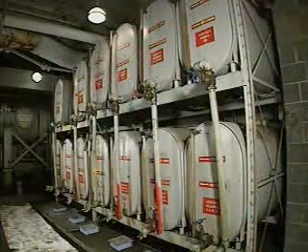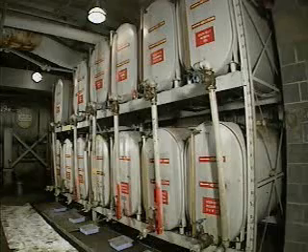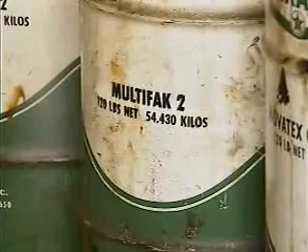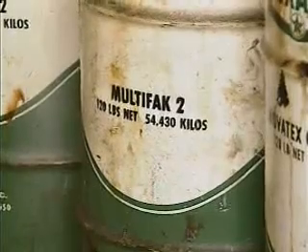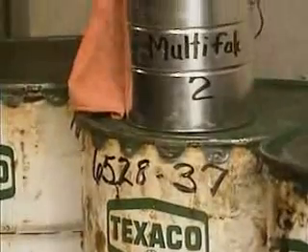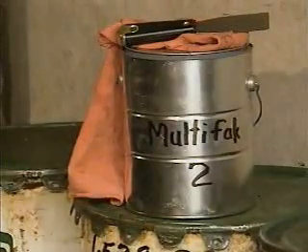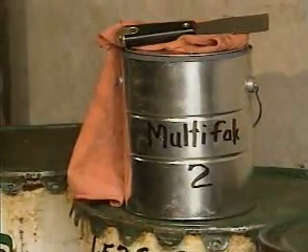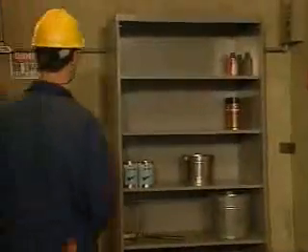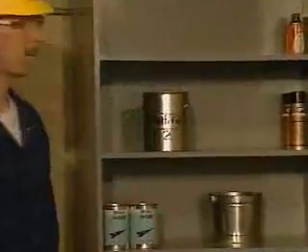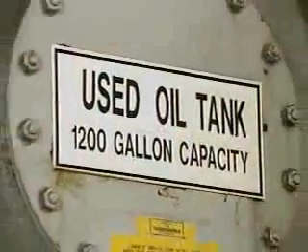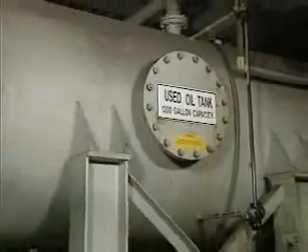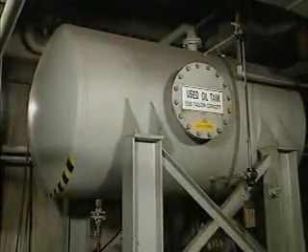When more than one lubricant is dispensed from the same location in a facility, it's important to identify each lubricant properly. Of course, the original shipping container must clearly state what lubricant the container holds. But any time a lubricant is placed in another container, the new container must also be clearly and correctly labeled. Lubricant should never be returned to its original container after it's been removed. That could contaminate the entire contents of the container. Likewise, contaminated or waste lubricant storage must be clearly marked.